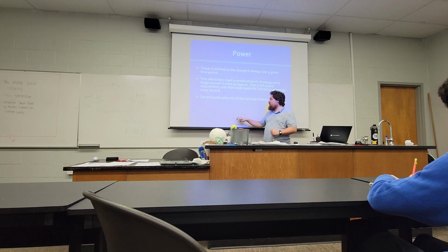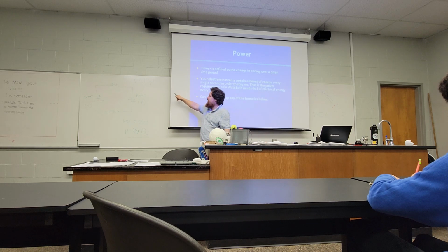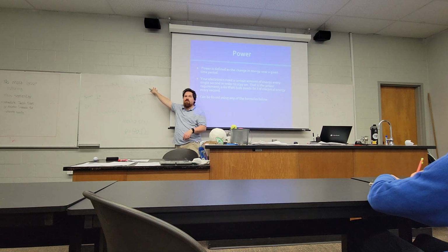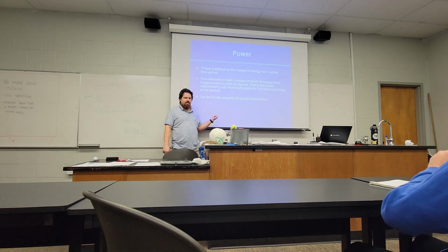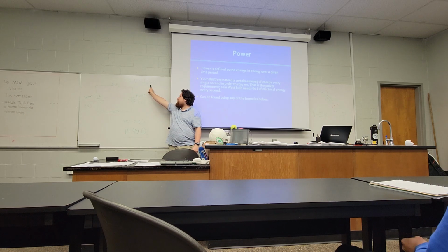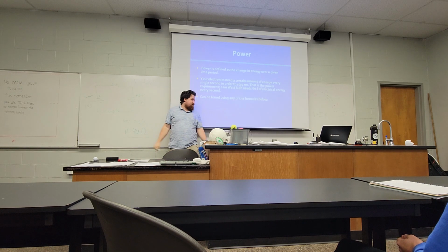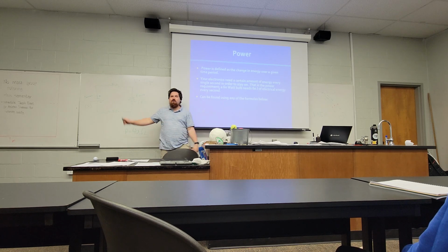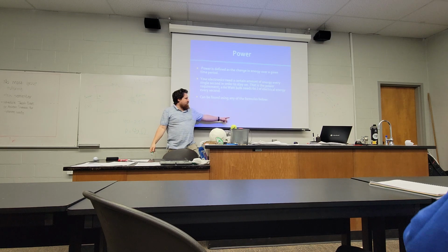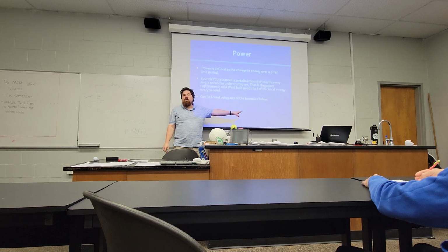And there's a couple other versions of the formula. This is just combining in Ohm's law to substitute around things you know or things you don't know. Since power is I times V, and voltage is equal to current times resistance, that means you can plug in current times resistance instead of voltage. It's already times I. So this here, I squared times R, is the same, just with Ohm's law substituting the voltage. So these extra bits here, they're useful based on what you happen to know.